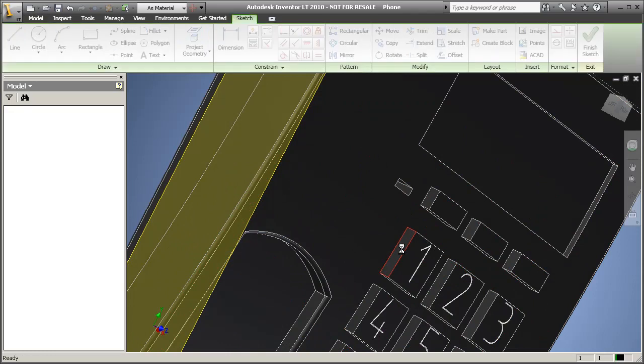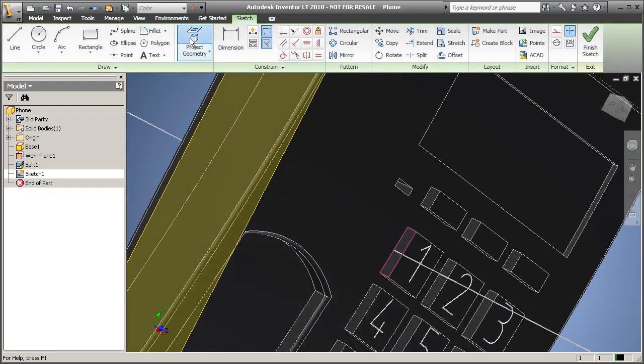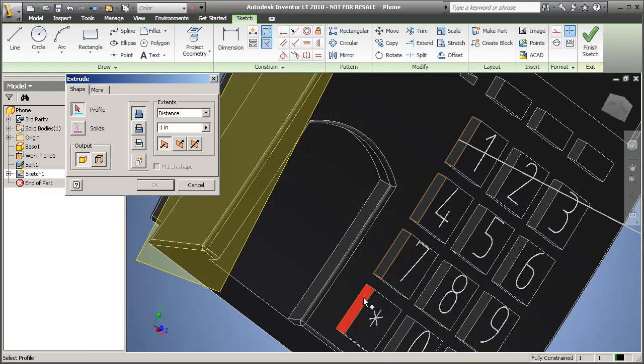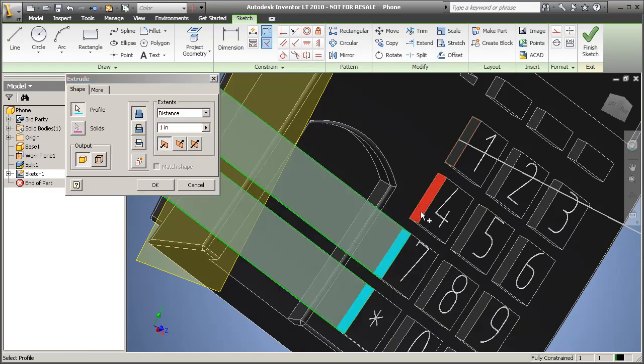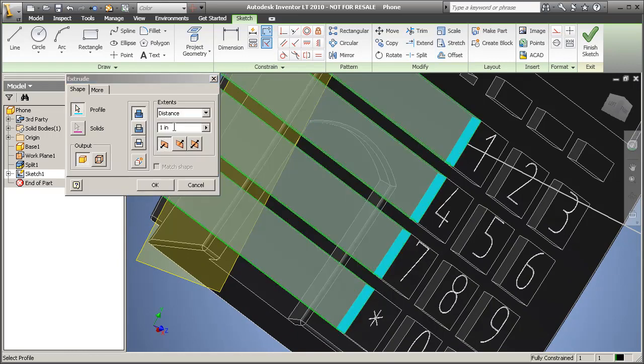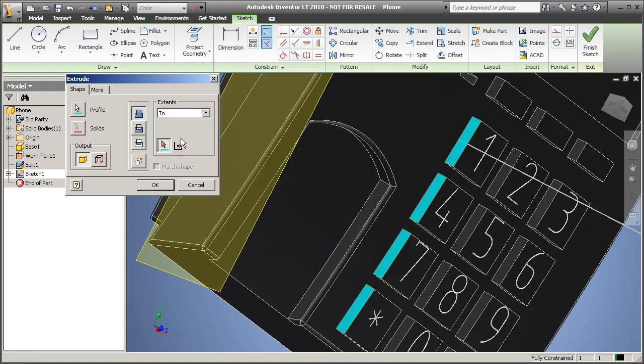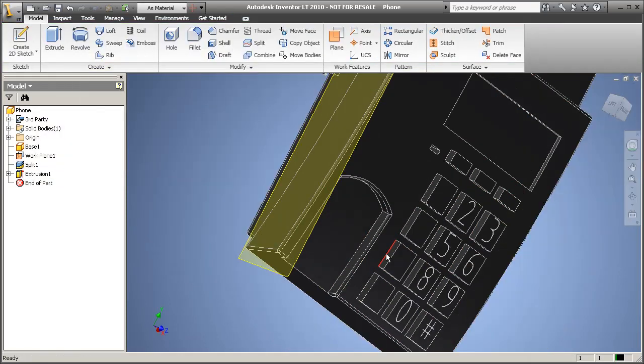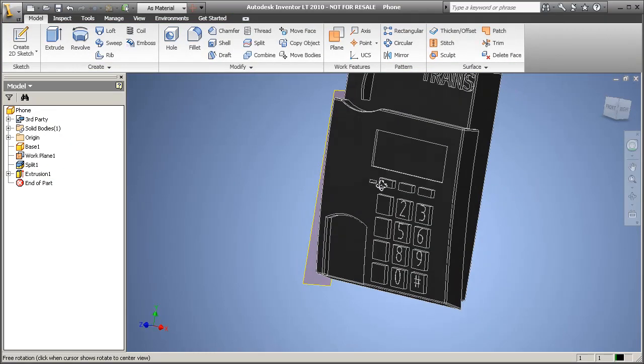So working with Inventor LT, I can do all my different part modeling. I can sketch on my faces, I can add, remove, and clean up these models. I can create models from scratch and detail them. For using it with BIM models, I want to clean these up. And notice they do come in as nice flat faces. They give me all the options to add and remove material. Here I want to add material, not remove it.